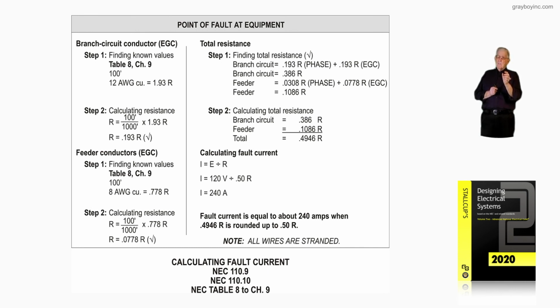So many times at a service, especially in a big commercial facility or an industrial plant, you're working on a stick of dynamite at that service if you do not have some kind of energy reduction devices, fuses or circuit breakers, which we looked at in Chapter 9 and talked about and gave you references to 70B and 70E, where you could just pick up all the information you needed to know about these devices.